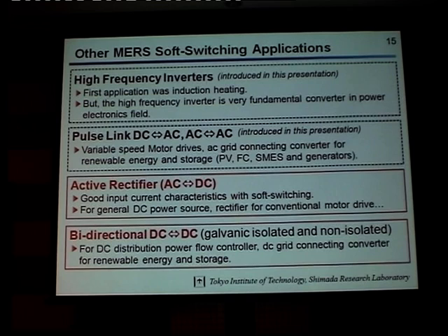May I add one comment, if you don't mind? Cost comparison has been done internally at our level, and cost is supposed to be theoretically a lot smaller than a conventional PWM controller, because number one, a heatsink is not needed, and number two, one less switch is required.